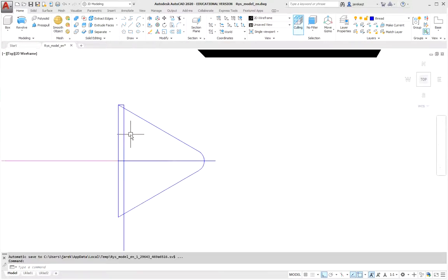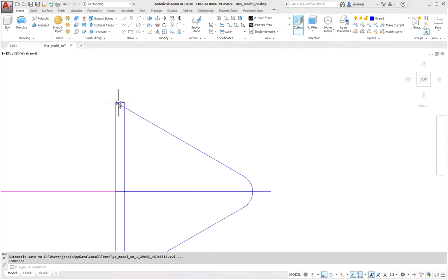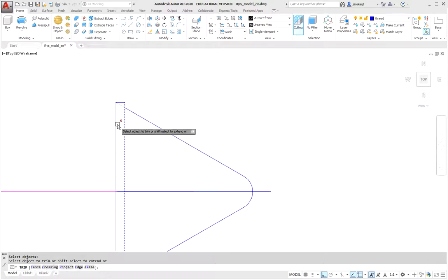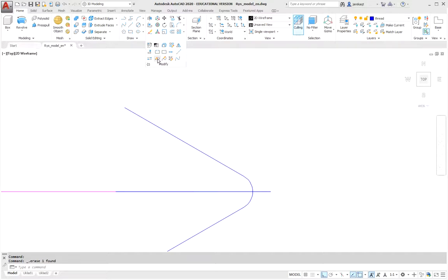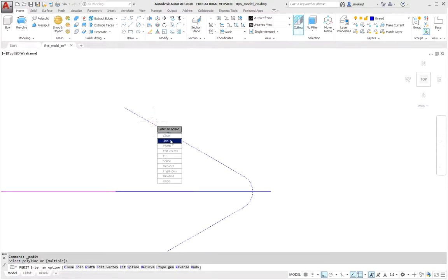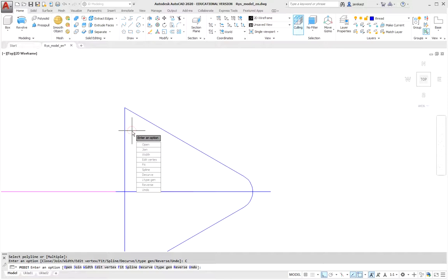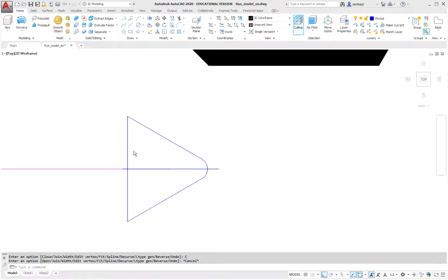To cut off the triangle so that it doesn't touch here, and cut it, we don't need it anymore because it was auxiliary to close it. And modify the polyline to close it. As it was drawn, it is a closed polyline now. Because to create the block, we have to operate on objects such that the polyline must be closed or it is a region.